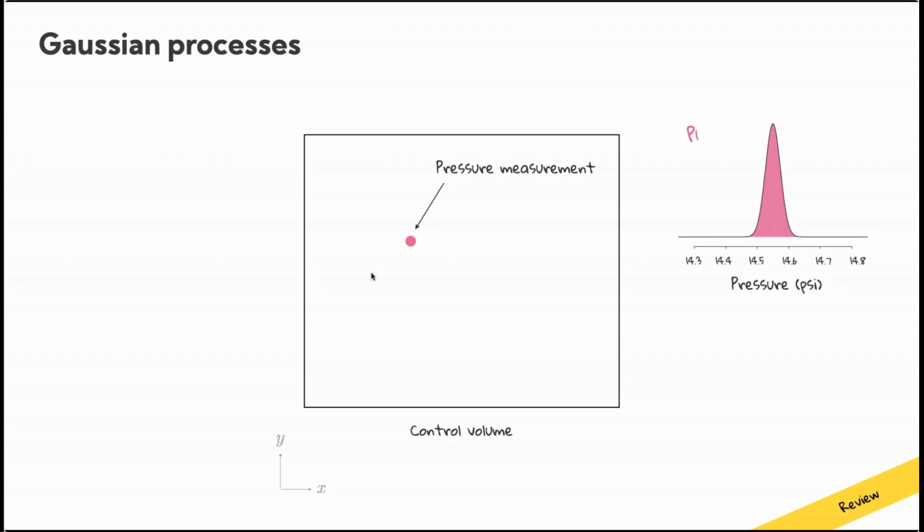But for those of you who are familiar with measurement paraphernalia, and indeed the measurement chain, you never actually have a single value for pressure. Pressure will have some variability, and that variability can be associated with either the imprecision of the sensor itself, or perhaps the uncertainty in the calibration that you apply when converting from millivolts to PSI, or the fact that there is an ambient pressure that you typically require in order to do the calibration.